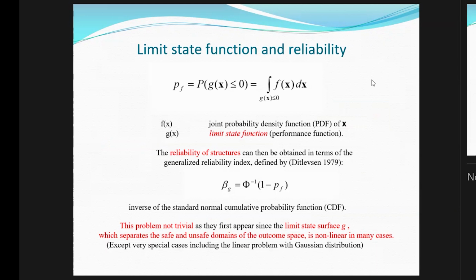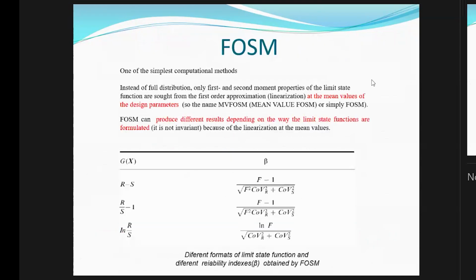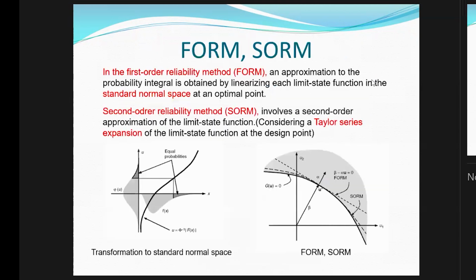For example, the bearing capacity of a column. By integrating the formulas for stability, we can use the inverse of the standard normal cumulative probability. We take into account the coefficient of variation of all input parameters, and we do a graphical presentation of the limit state function of the failure. Everything on one side is good, and everything on the other side is not good.